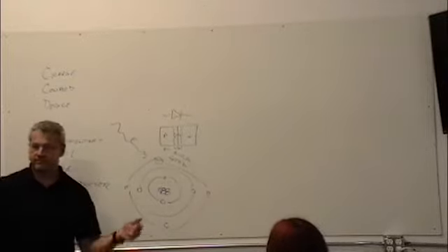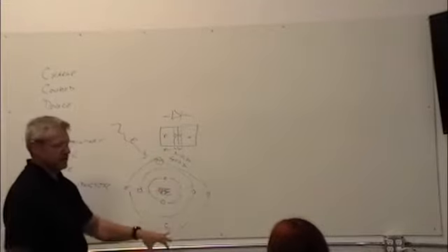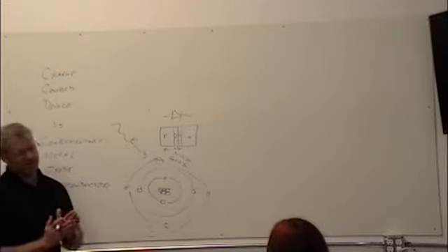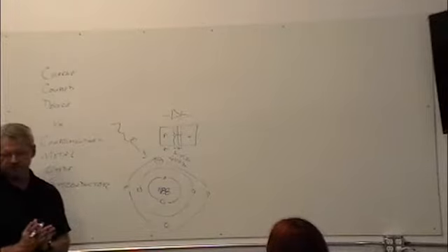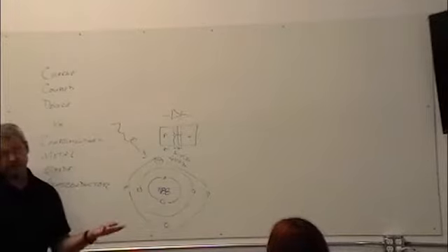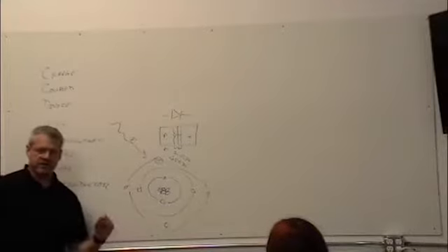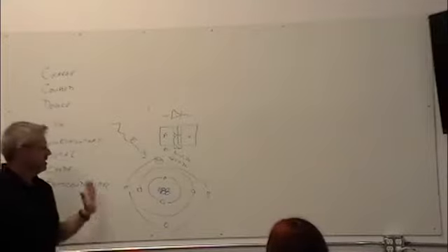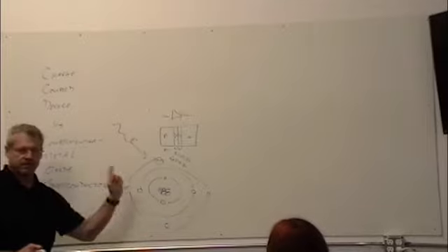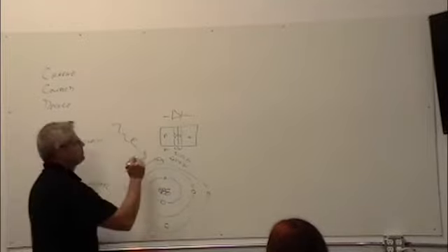Happens all the time. Light comes out. It turns out that light in the band of sun on the low frequency end of ultraviolet all the way out, which is 300 or so nanometers wavelength, all the way out to near infrared around 1.1, 1.2 micron wavelength is enough to make that happen. In silicon, it's a 1-for-1. You get one in, you get one out.